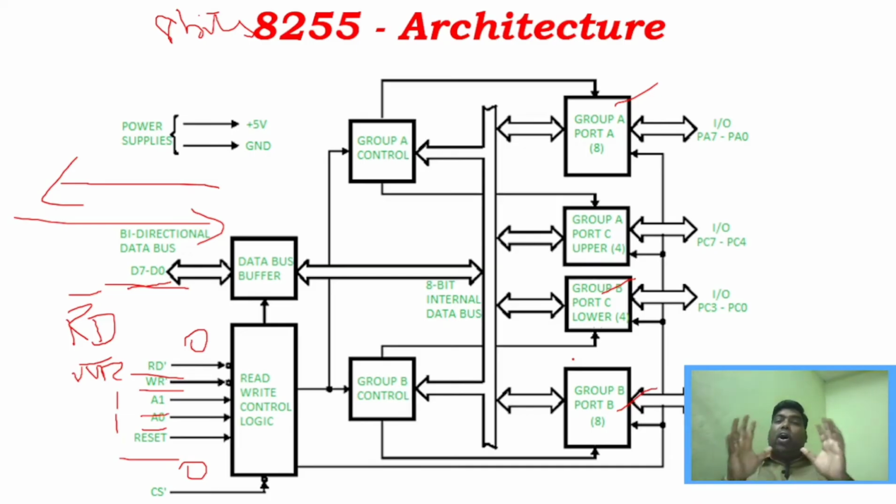But as of now, this is the architecture of 8255, where I have explained these different ports as well as the data bus buffer and read write control logic. And very importantly, as I said, we have group A control and group B control. This group A control and group B control will get the control signal from the control word, and this control signal will be sent to group A or group B, depending upon the control signals. And as I said, these ports are input output ports, all are bidirectional ports.